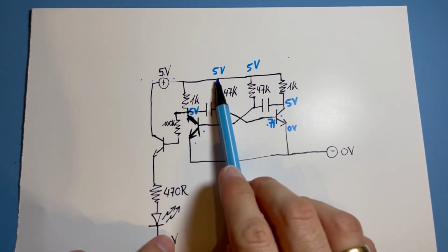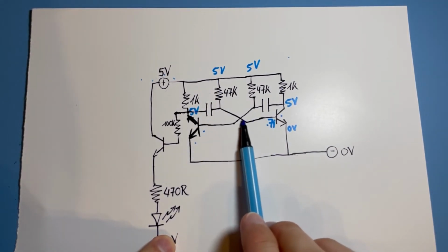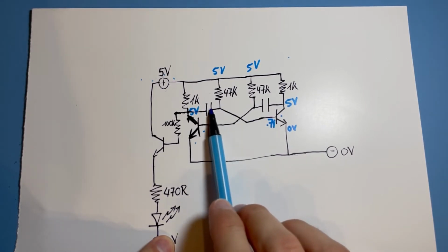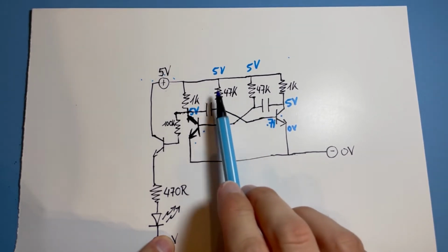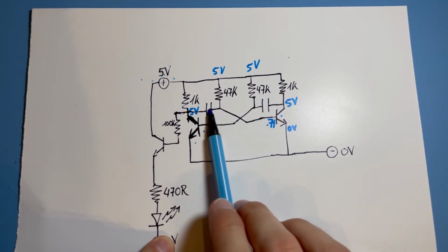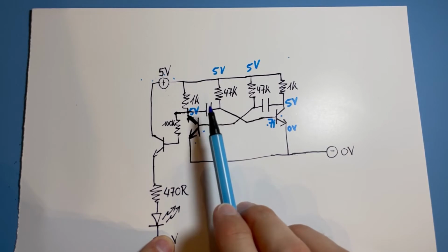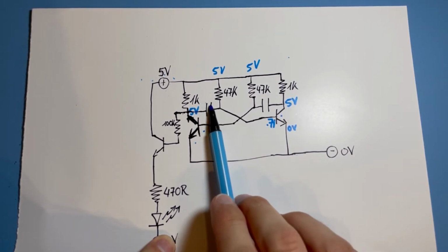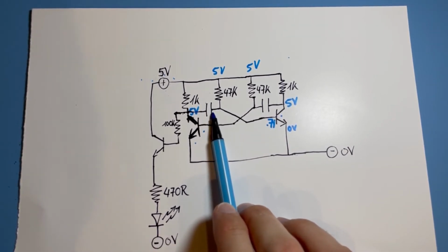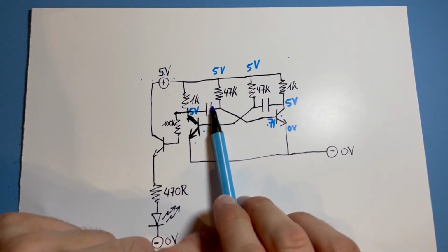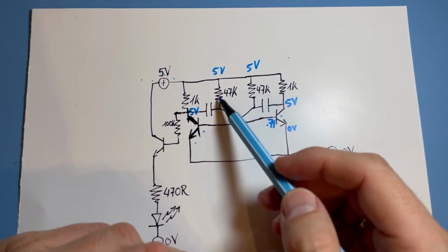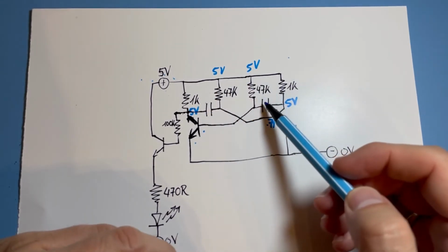And as you know, everything on this path in between the resistor, the capacitor, and the transistor, every part of the conducting line has to be at 0.7 volts, so must be the right side of this capacitor. And for a capacitor to charge up to 0.7 volt, it's like through a resistor, you have to first load it, and it takes some time. This capacitor loading takes some time, and this capacitor loading takes some time.